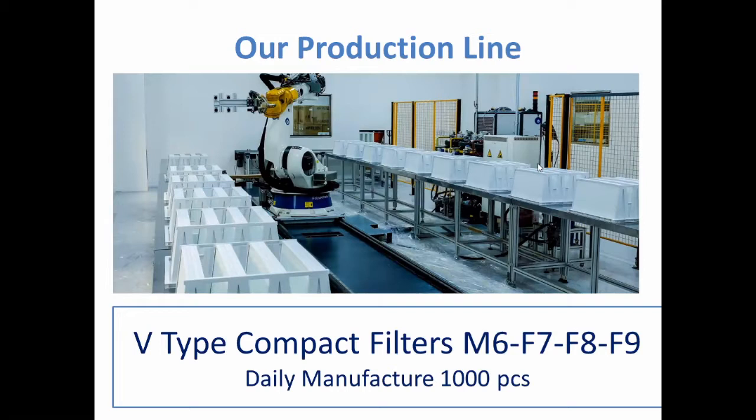And here is the production line of the rigid bag filters. We have a robotic system to apply glue on the filters. We have the efficiency rate from M6 to F9, and they manufacture, I think it was over 1,000 pieces. Exactly, it was around 1,300 pieces daily with one worksheet.